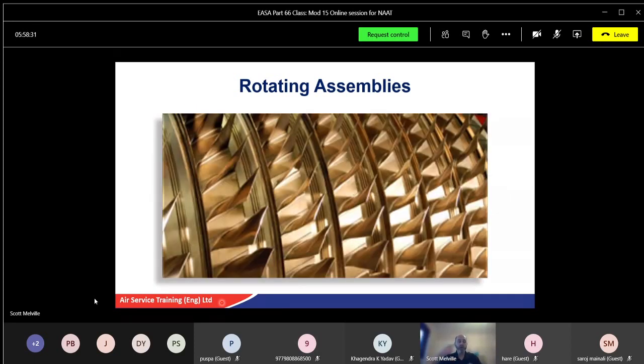So sometimes as well, when you're spinning the rotating assemblies, it's important to know the number of blades in a particular stage. So you can be spinning around, and you need to know, have I gone around enough blades? As you've got the person rotating the gearbox, you'll be counting the blades nice and slow. Let's say there's 30 blades on a disc. You'll find one blade that's maybe got a specific mark on it, maybe a bit of dirt. Use that as a reference, and then get your colleague to spin it. And then once you've counted the blades, and you're happy you've checked all blades, that's fine.